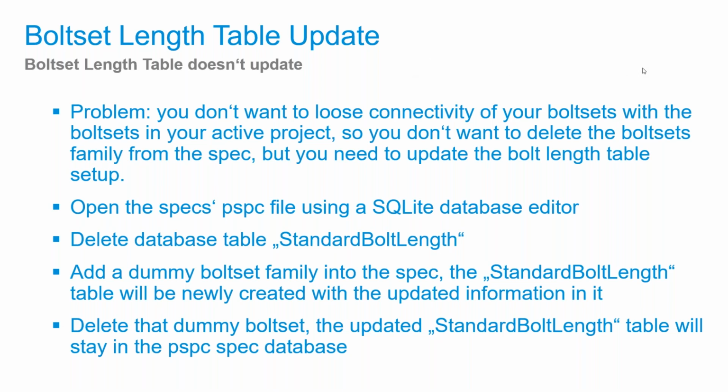So what we found, and this is not a very common example, is that a customer had to edit the bolt set length table. These are where you can set the default tables for the bolt lengths, and where you can also add additional tables that will be connected to this property, which is called compatible standard, bolt set standard, which is of course a different topic.